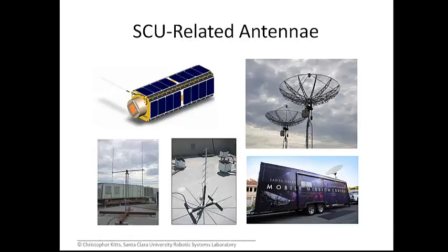Down on the left, you see what looks like sort of an H configuration. Those are long Yagi antennas that are oriented up and down, and they're both supported in the middle by a cross brace, so they both run off the same position control motors. But those are anywhere from 15 to 20 feet in length, and so they have pretty high gains on the order of roughly 15 decibels or so. And one of those is used at UHF, and the other is used at VHF frequencies.